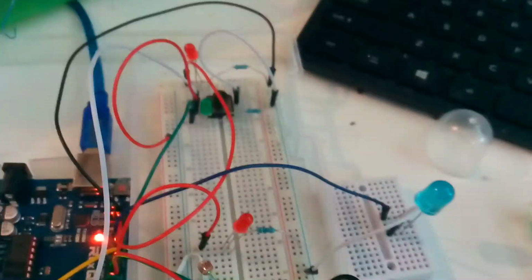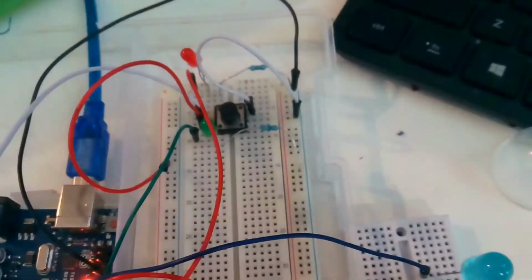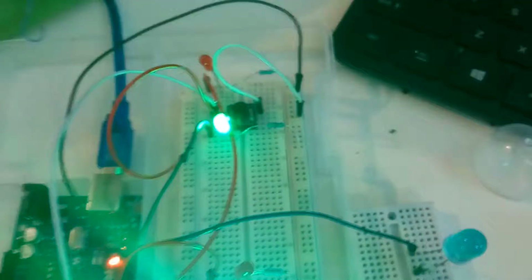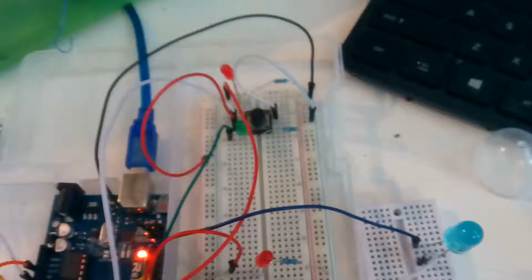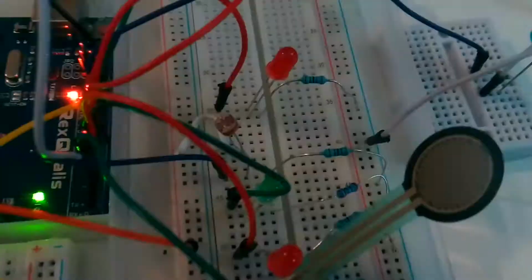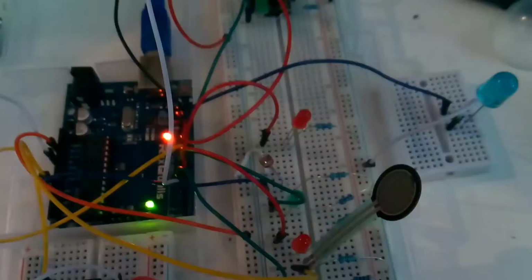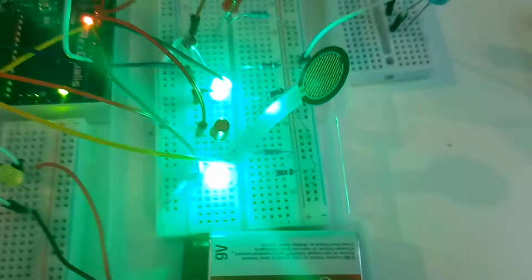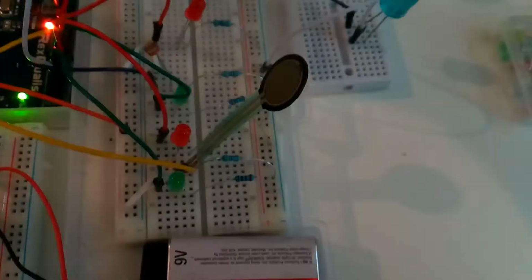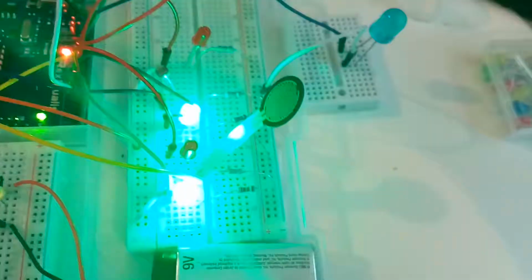As you can see here, I have 3 stations. The first one will be loading and it's user operated using the push button. Whenever the operator finishes the procedure, they push a button to allow it to move to the next station, which is the dimensioning, which uses laser curtain and laser lights to measure the product. So I have a photoresistor there to check the light values. And then the final station will be the weighing. I have a pressure sensor there to check the reading of the weight.